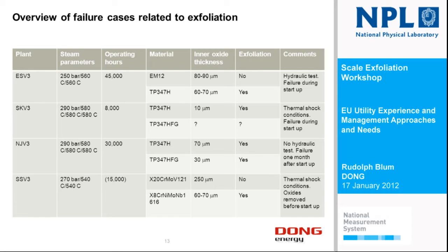After some years in operation, for some reason, somebody found out that they had a blockage. But we found this blockage before startup of the plant, thanks to X-ray, and it is a pendant superheater. Thanks to X-ray, we could find all the blocked bends, and we cut them out, we cleaned them, and we put the boiler in operation. So no problem.